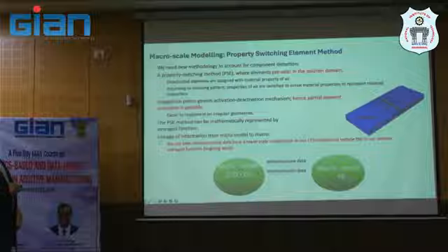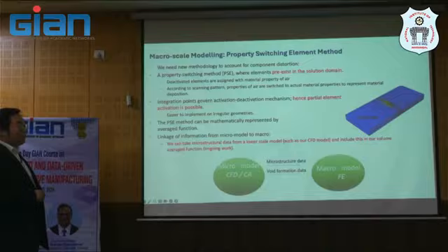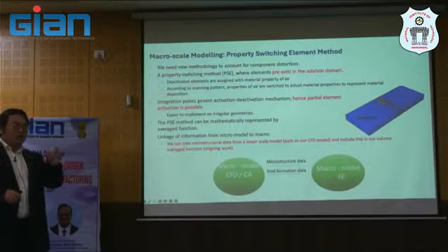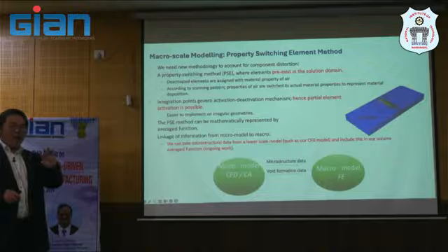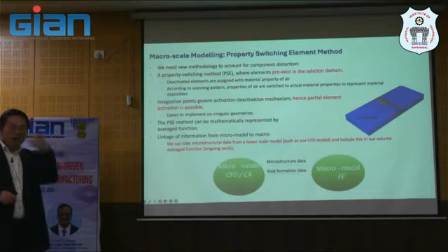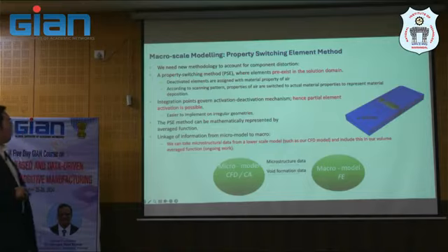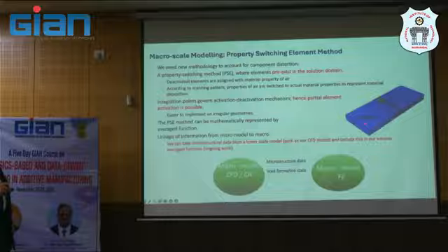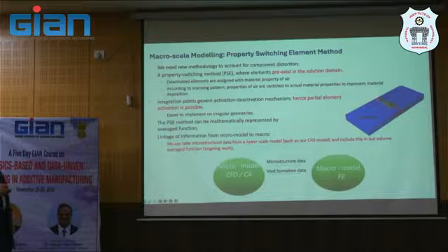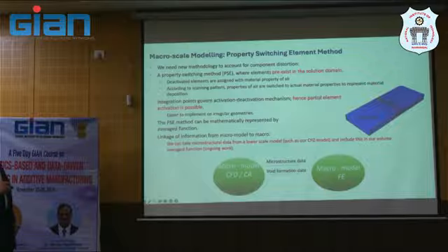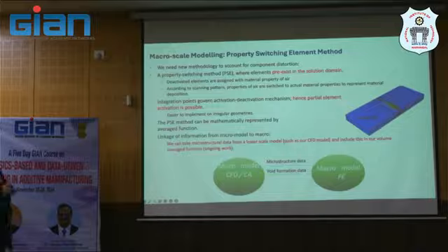So the material property is important in this case because you need a function that can switch the property considering air and material and powder at the same time in a voxel, or in a calculation cell that you do. So again, people are trying to do this and validate against experiment like we do, and we will show you a little bit later. So you will know that this will be good.